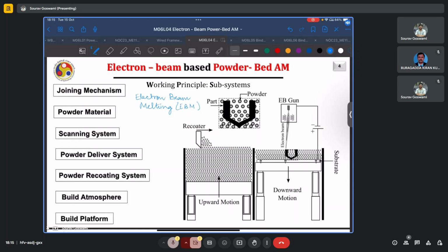However, in cases where we fear that there might be warpage of the parts, we may have to engineer some explicit support structures. Again, it is not to prevent that overhanging structure from falling down under the action of gravity, but rather to prevent it from warping upwards and colliding with the recoater blade or some other part of the machine.